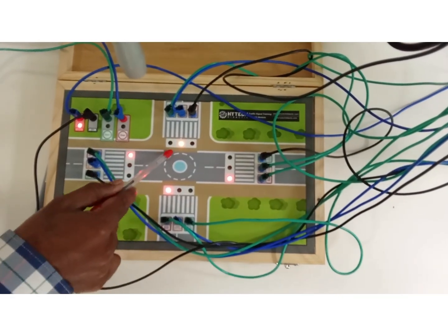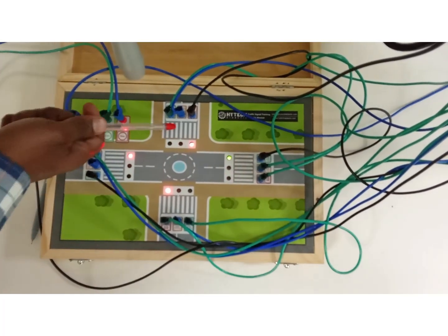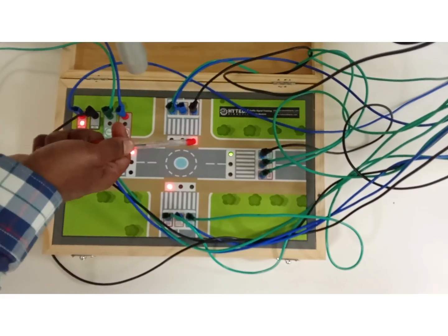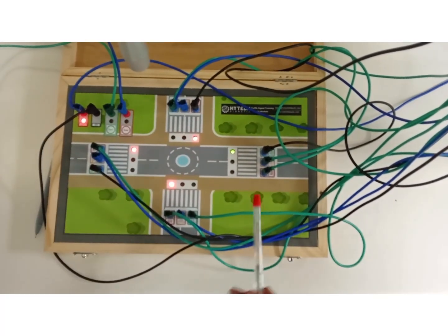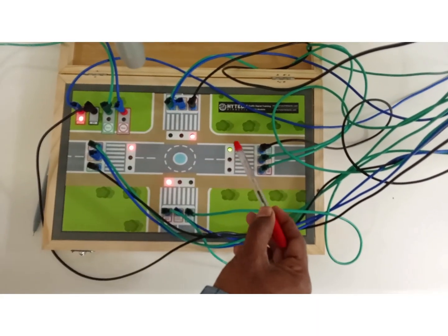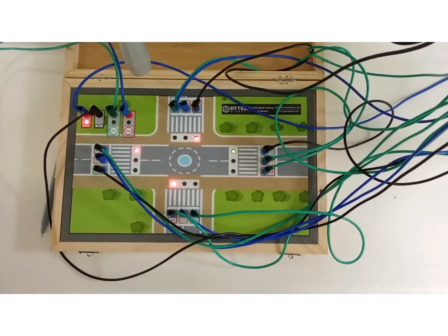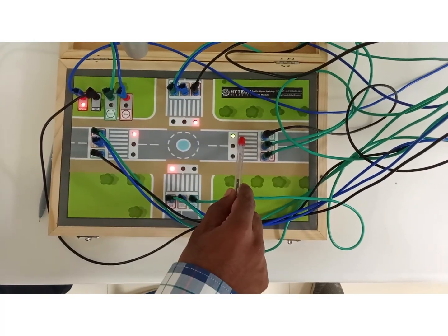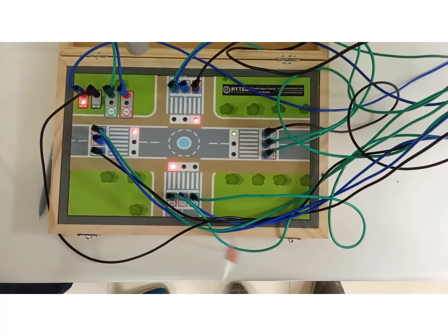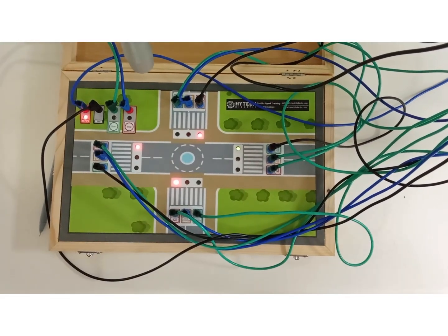In the next 5 seconds it will shift to yellow. Afterwards, after 5 seconds, it will automatically shift to red and transfer to route 2. In route 2, the green color is on and the timer counts from 30 to 55 seconds. Again, for 25 seconds this green color is on to allow the vehicles to pass. Afterwards it will shift to yellow, then to red.